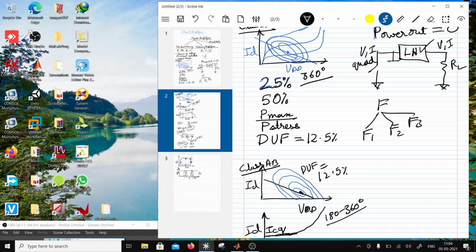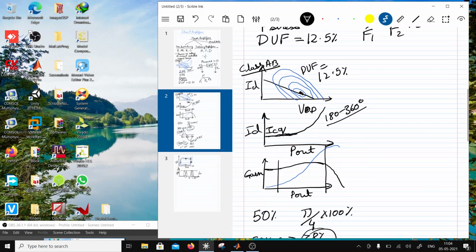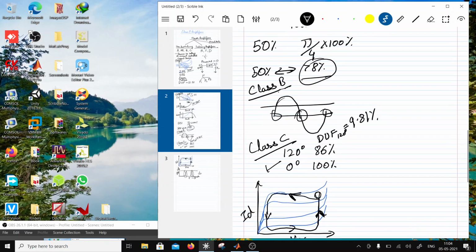So an idler would be typically, let's say, this circuit. At thrice of f0, I have an idler. That means that this is going to anti-resonate at third harmonic, and then I have an idler at fifth harmonic and seventh harmonic. So this will cause all the odd harmonics to be able to propagate to the device, and then to the load, and then you are going to have this square waveform of voltage and current.